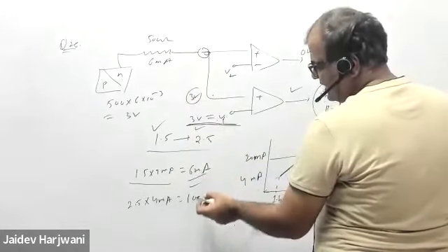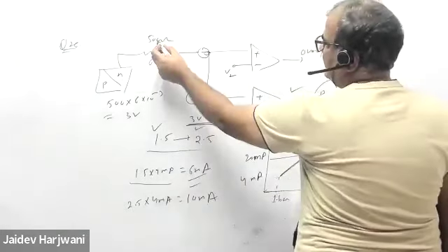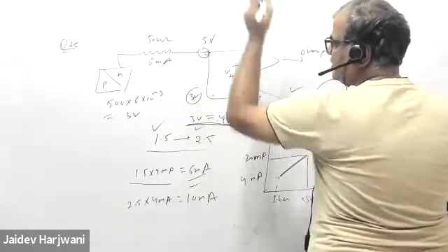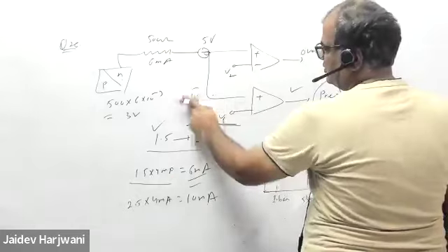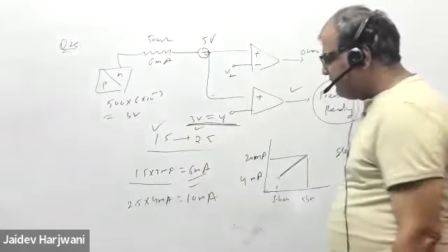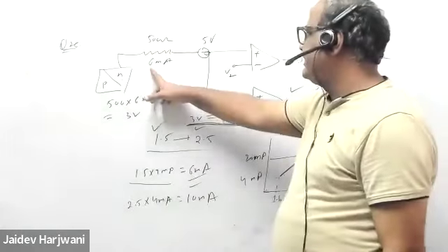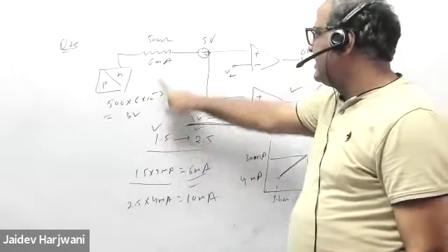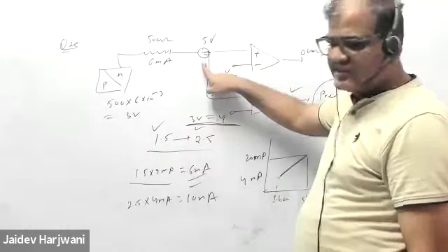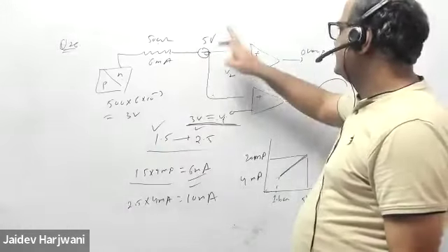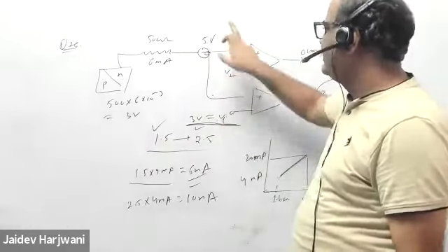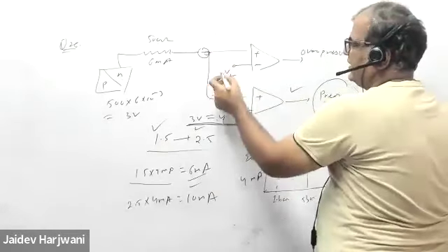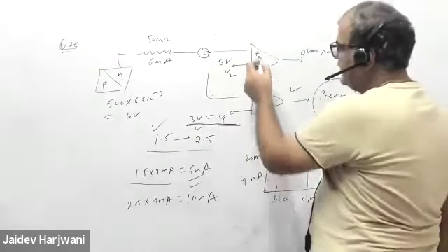For 2.5 bar, current should be 10 milliampere. So 5 into this should be 5 volt. So current can come from 6 milliampere to 10 milliampere. Then first it will say it is ready when 1.5 bar is reached, and when 5 volt comes, it will say stop, the pressure range is crossed. So this should indicate when V2 is 3 volt and 5 volt.